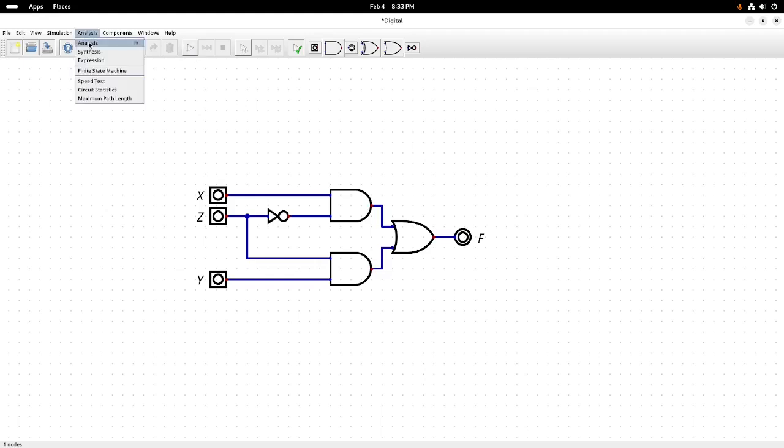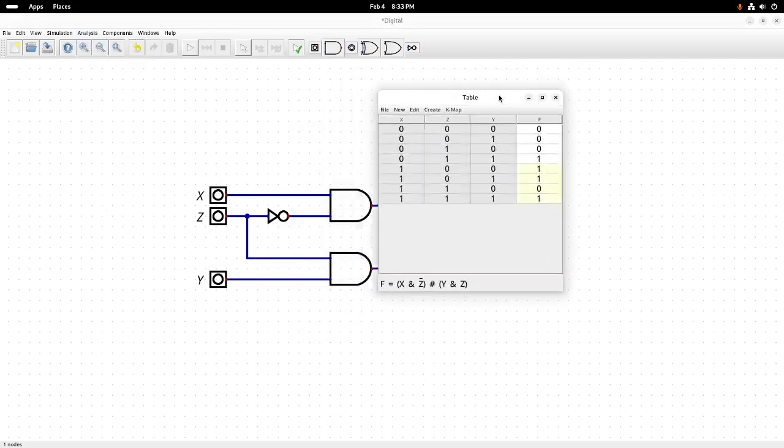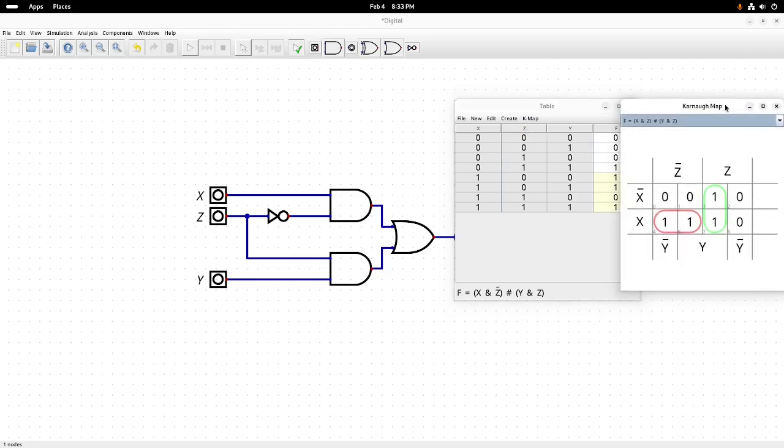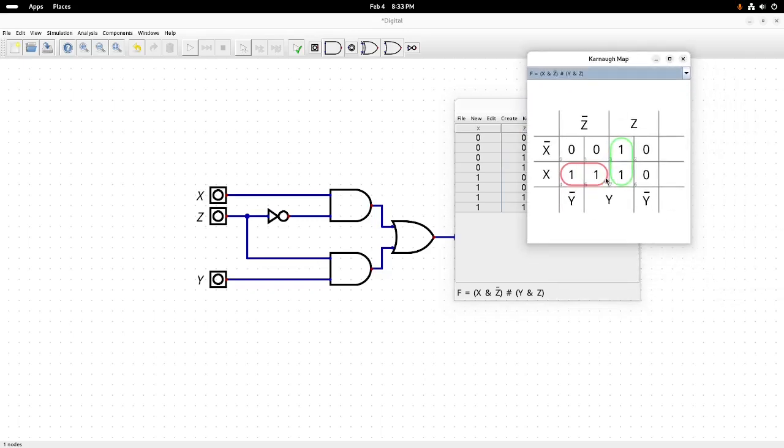If we do an analysis of this, it's not going to warn you, "You screwed up. There's a static hazard glitch." And if we look at the Karnaugh map, you will know that to get rid of the static hazard glitch, you have to draw a little circle there.